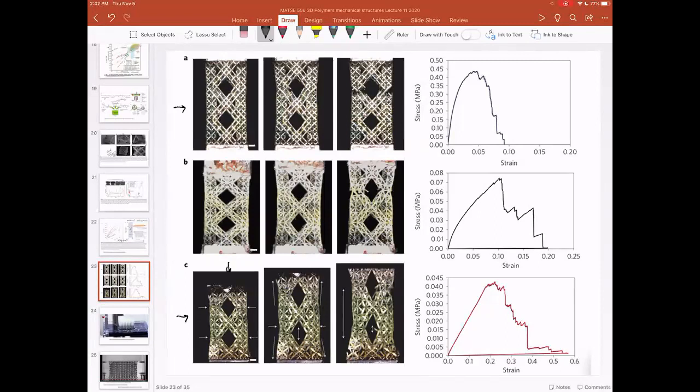So some parts stretch, some parts compress, and then that's what gives you these high strains where you have, in essence, graceful failure rather than everything going to pieces all at once. And so this idea where now you can control the deformation of the structure depending on how you print it is very interesting because you're not stuck with the same thing over and over.